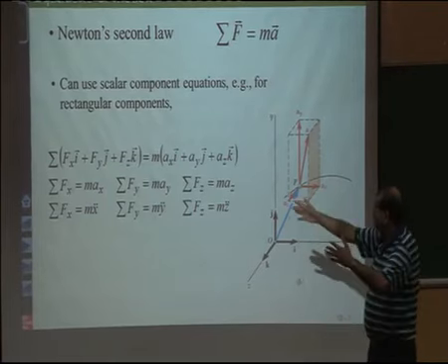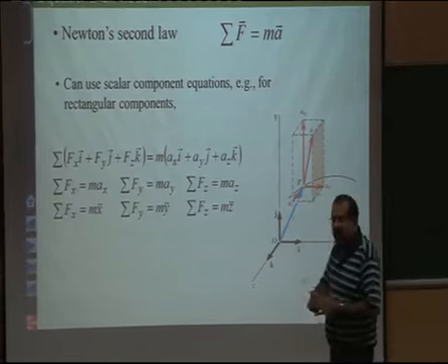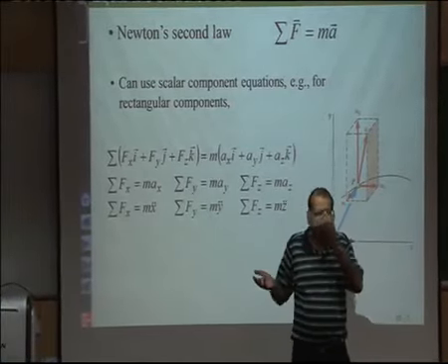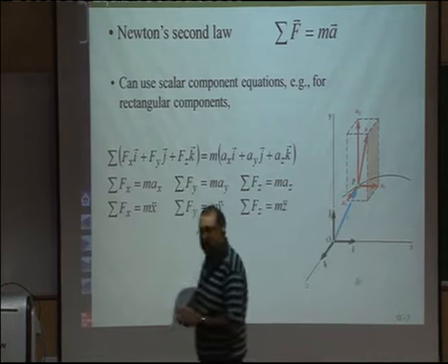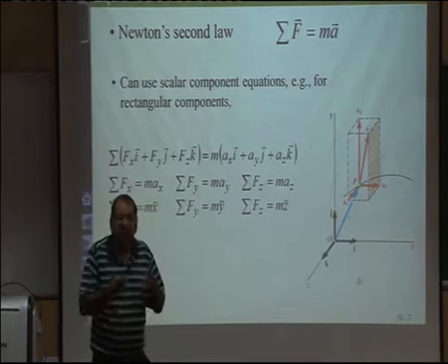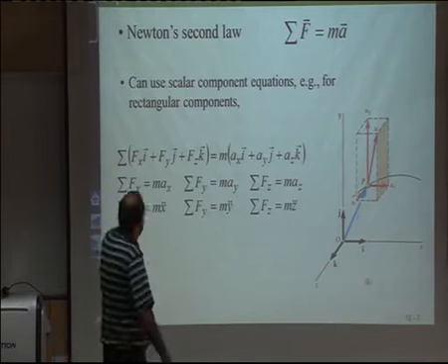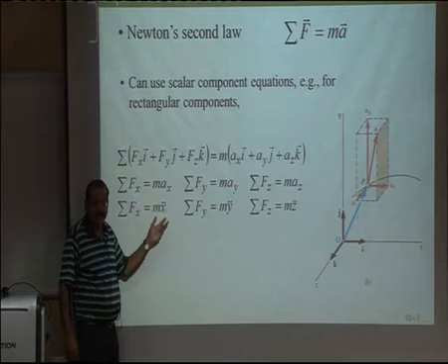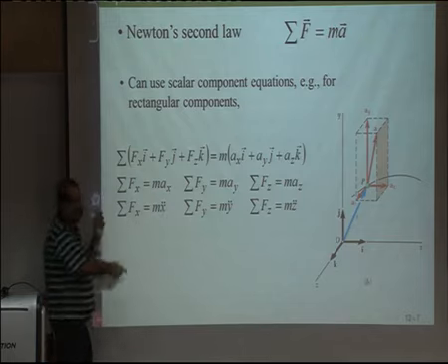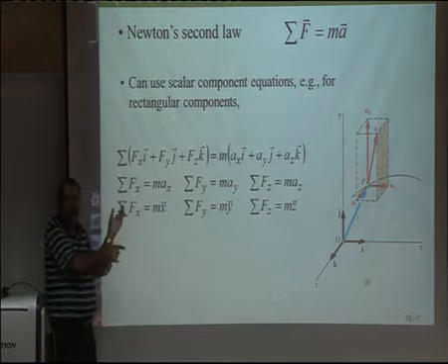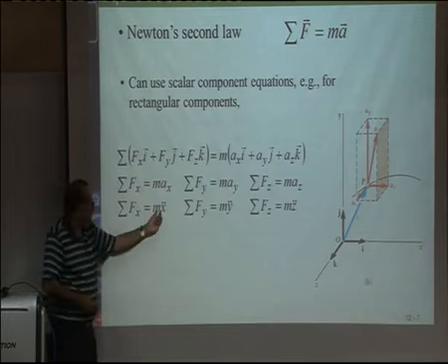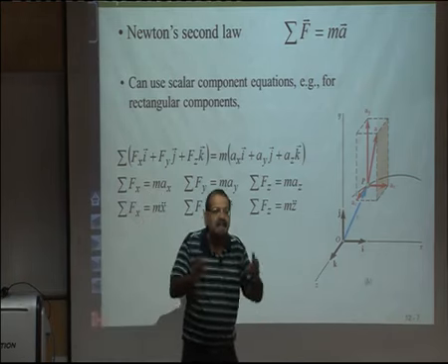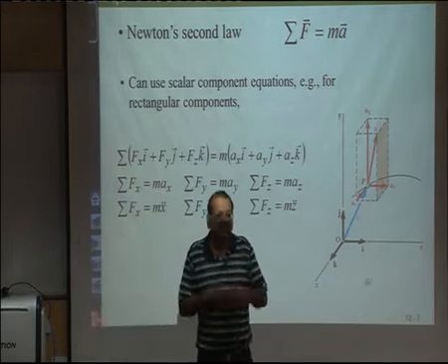So, this is the basic equation. Then, if force is known as a function of time, we'll integrate this. But that gives rise to another formulation which we call the impulse momentum form. What we do is write Fx is equal to m times d(x dot)/dt. And if x is a function of time, then we integrate this with time. So the integral of Fx dt becomes m times the change in linear momentum, and the integral of F dt is what we will term as impulse.